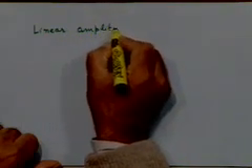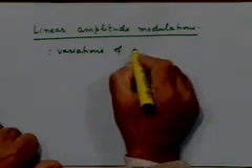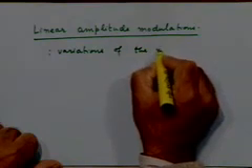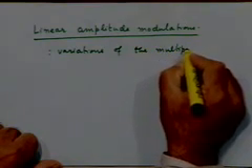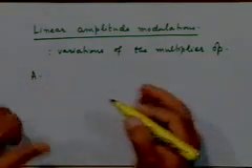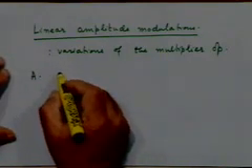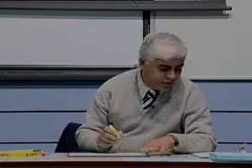Now this basic operation forms the basis of all linear modulations, or what we call linear amplitude modulations. So all these linear amplitude modulations are basically variations of the mixing, the multiplication operation that we discussed earlier. Right? So there are variations of this. Let's discuss these variations now. The simplest is just this process that we have discussed. Our starting point could be just this very modulation, namely multiply m of t with cosine omega ct. We know that this will lead to frequency translation, as we will soon again review.